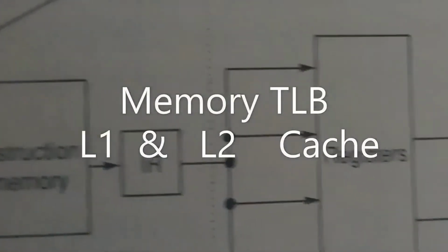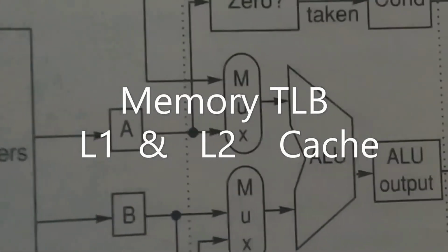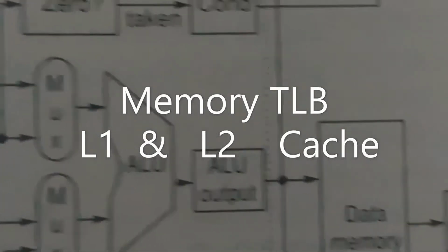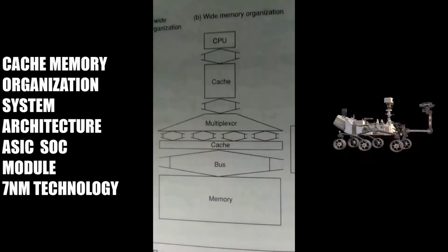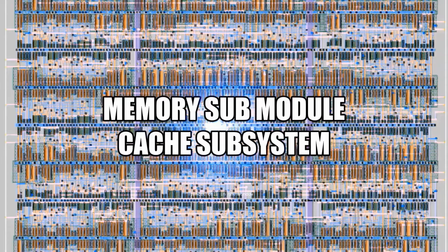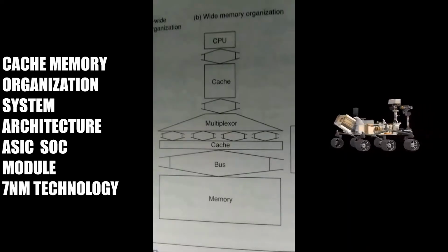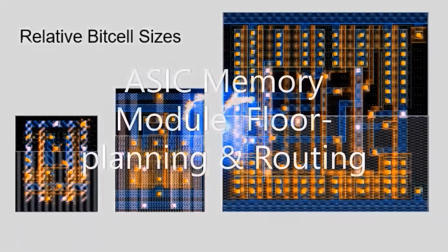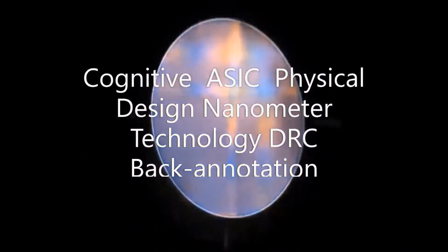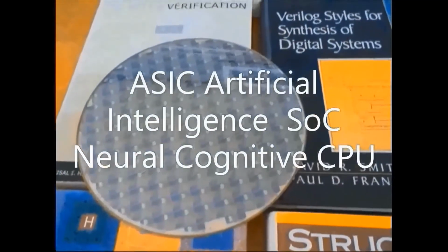and this memory chip can be organized in banks to read or write multiple words at a time rather than a single word. In general, the purpose of interleaved memory is to try to take advantage of the potential memory bandwidth of all the chips in the system. In contrast, most memory systems activate only one, containing the needed words.